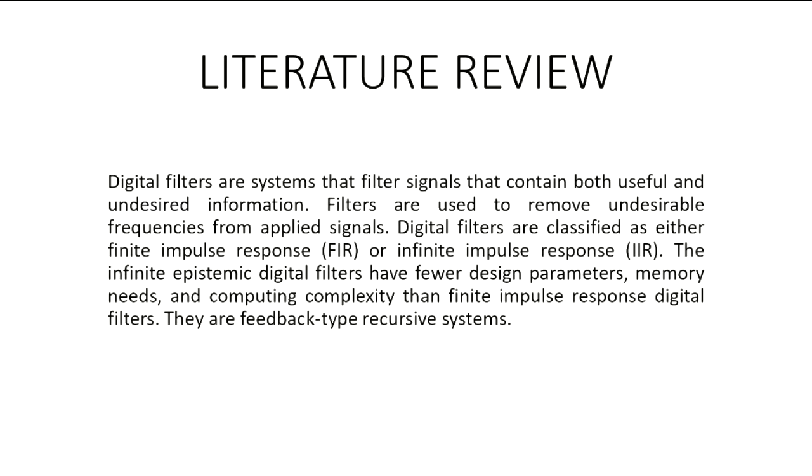Digital filters are systems that filter signals that contain both useful and undesired information. Filters are used to remove undesirable frequencies from applied signals. Digital filters are classified as either finite impulse response, FIR, or infinite impulse response, IIR. The IIR digital filters have fewer design parameters, memory needs, and computer complexity than FIR digital filters. They are feedback type recursive systems.